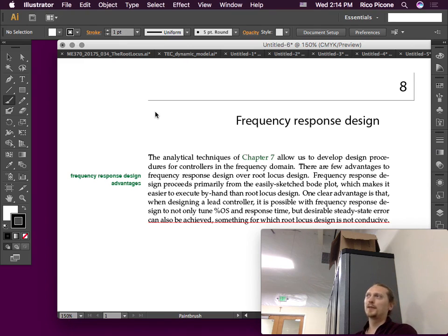And it's only with the one that we're going to go over today, the gain one, that it's a pretty straightforward technique that you can reproduce on lots of problems. But it's only gain control, and that's it. The lead and the lag lead stuff, there are some techniques, but they don't always work on everything. So I'm going to encourage you to lean more on root locus design for your controllers, but in some cases, it can be advantageous.